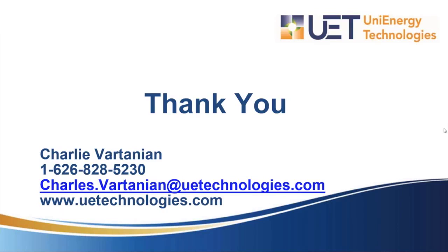Okay, very good. And what is the conversion efficiency of flow batteries when you include pumps and other balance of power and parasitic loads? I'll chime in for UET, and Summer might have a more general view. For UET, at the DC level, it's 80%. The power conversion itself is another 4%, and the parasitics, the pumps, the house power, is another 6%.